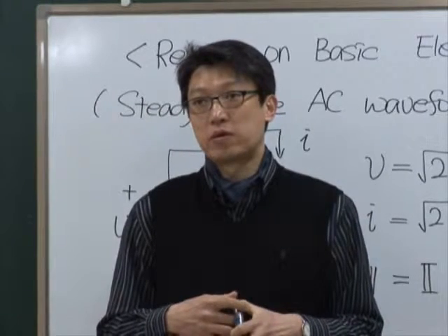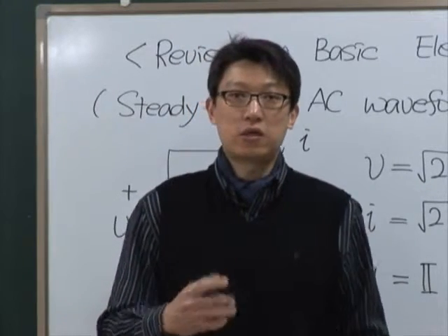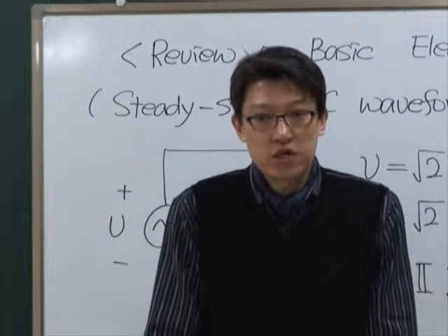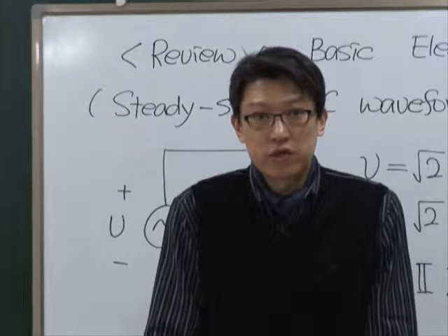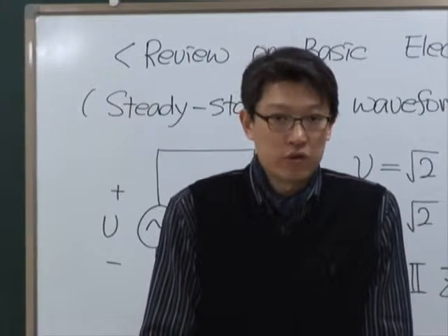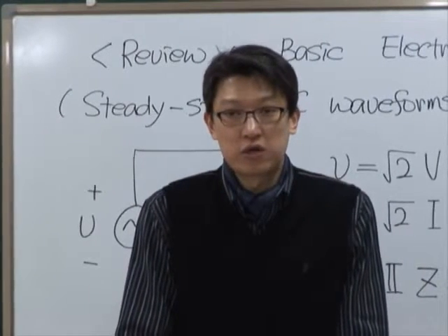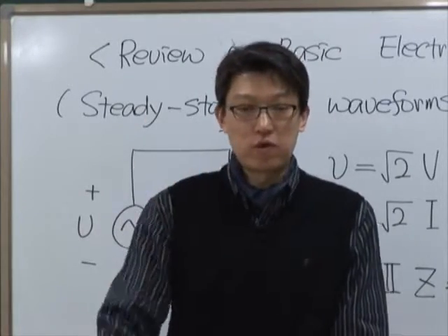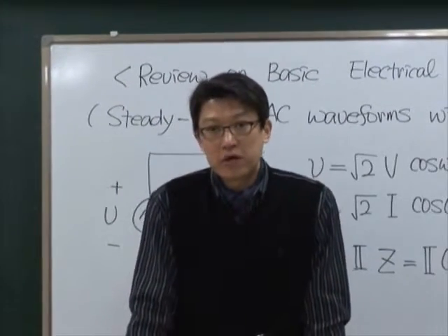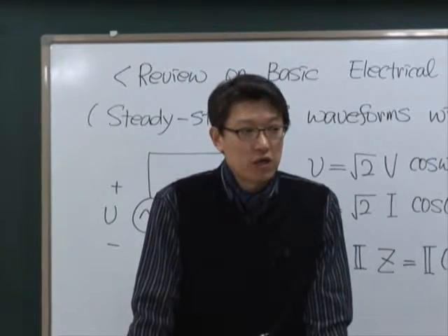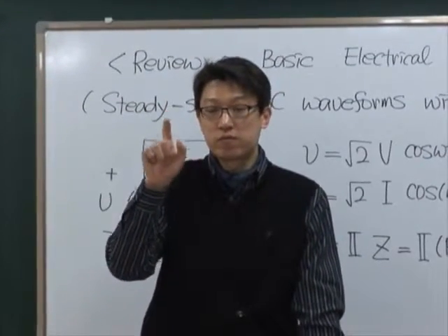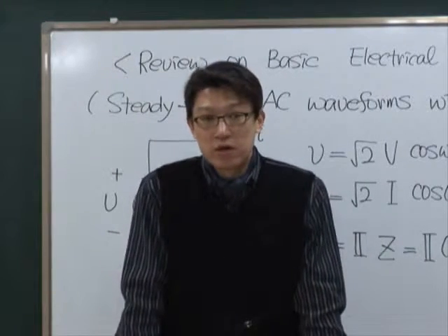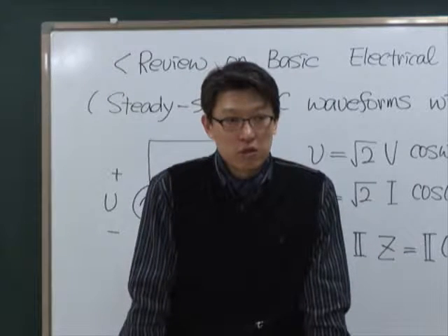So we're going to discuss these definitions of power. One key concept of power electronics is switching. Okay, switching. The thing that differentiates power electronics from other courses is that we are using power semiconductor switches, switching on and off, on and off. So when the switch is operating, the voltage waveform looks like a square waveform, right? When the switch is operating, the system becomes no longer sinusoidal.